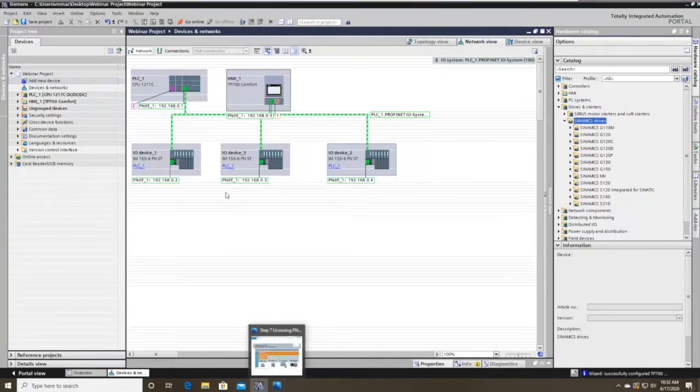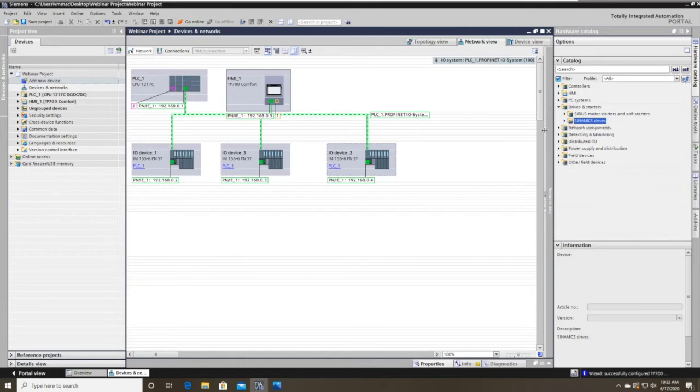So in this instance, you would have your PLC, you have your 3 remote I/O set up, you have your HMI, you'd have your drive. And for most people, that would probably be a decent setup. Those are all Siemens devices, so that's very appropriate for a lot of people that are using Siemens devices. But say you didn't have a Siemens device and you wanted to add that to your project. Well, it's not going to automatically appear in your hardware catalog because it is not native as a Siemens device.